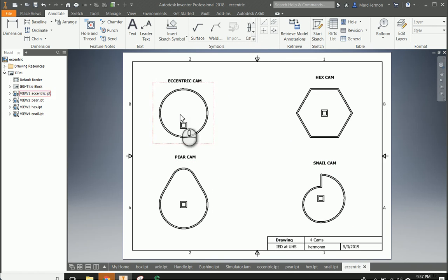So we want to maybe click the centers, the center holes. These are square axle holes, so we can't actually do center lines in there, but I'm going to click on this whole circle, so it puts a center mark in that. On this one, you'll have one there, and you'll have one there. So that's good. We need those in there. Okay.